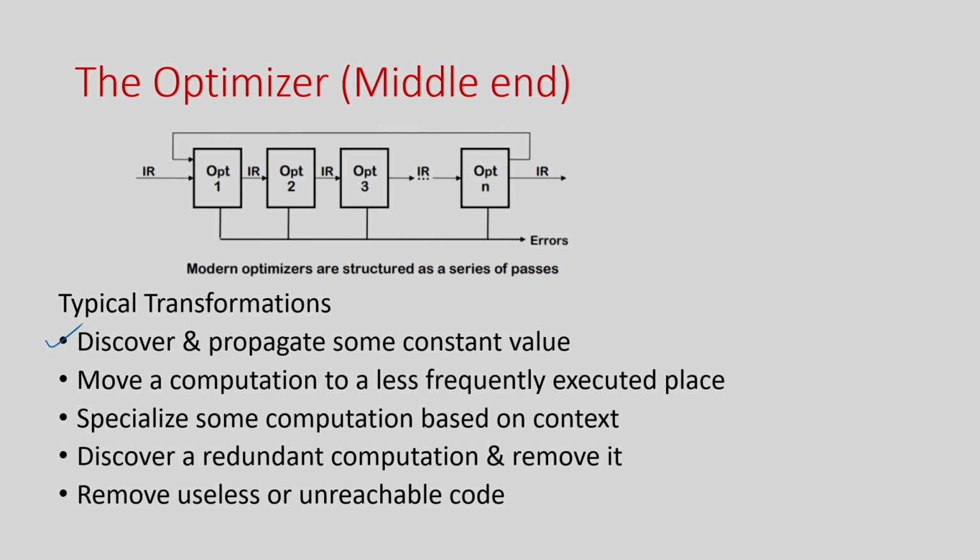Now, in the context of high level synthesis, we term this optimization a front end optimization, because this is what happens before the actual processing done in the high level synthesis, right. We can consider scheduling, allocation, binding and data path control as the primary phases of high level synthesis, and this is the front end, right. And since we integrate GCC or any other compiler into the HLS flow, we can always enable or disable these optimizations, right, and they will impact high level synthesis, right.